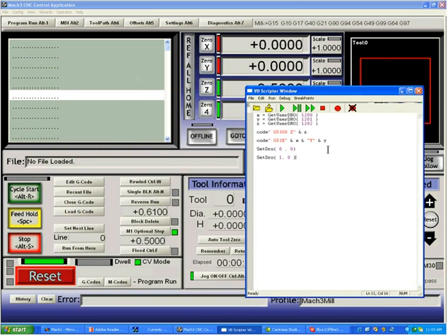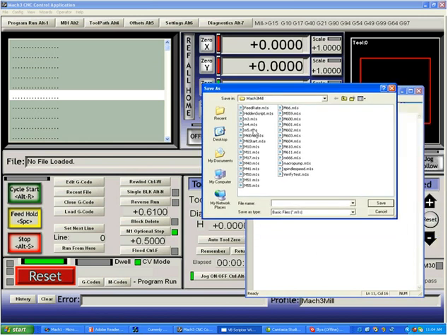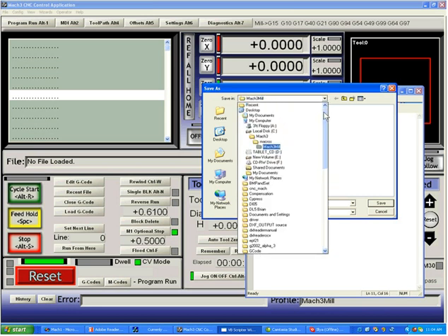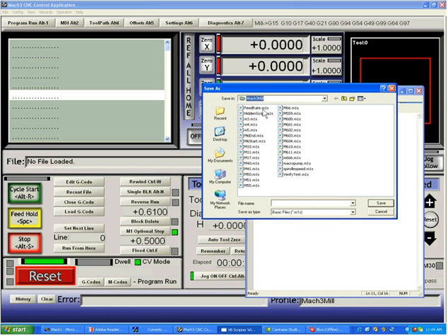Now let's say that we want to do this whenever we're going to do a tool change. I'm going to hit File, Save As. Now, the macros and the files that are run as macros in Mach 3 are tied into the profile macro directory of your system. If we take a look at the tree here, I am in Mach 3 macros, Mach 3 mil. Now you may or may not be using the Mach 3 mil directory. If your profile is called My Profile, then you would be in Mach 3 macros, My Profile, and in that folder you will find all of your system macros.